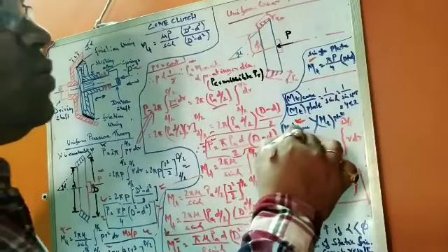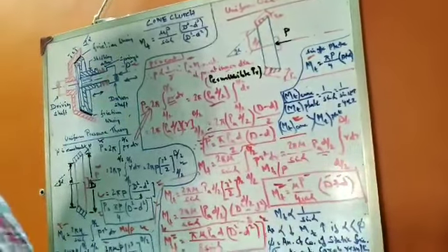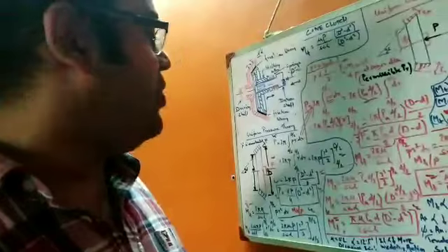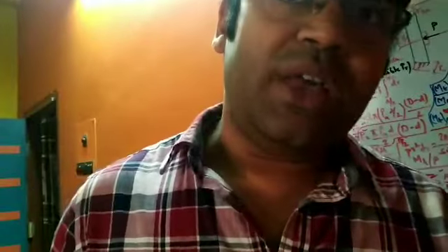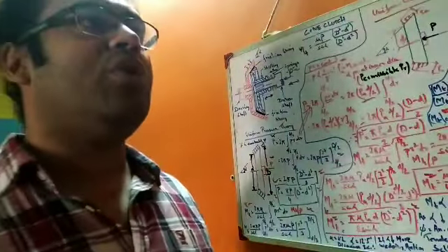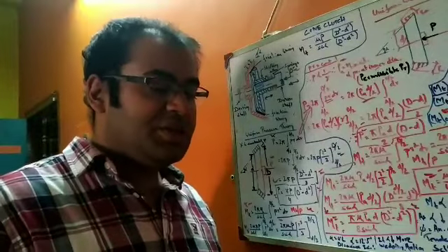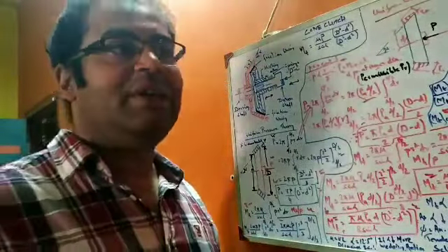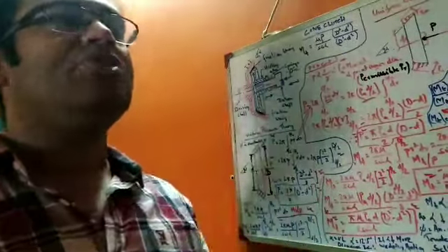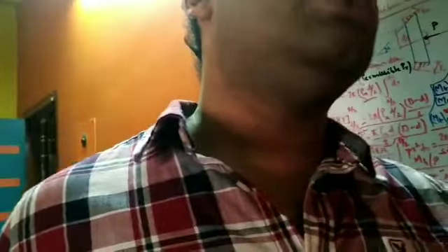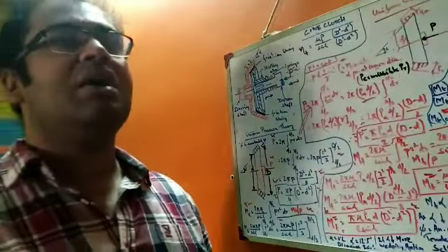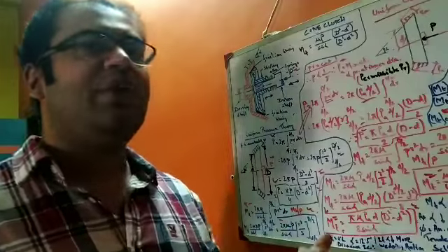That is the reason behind using the cone clutch. The boundary conditions for solving the integration from the elemental area to the whole clutch depend on two theories. Number one is the uniform pressure theory, for which we have calculated the applied load required and the frictional torque transmitted.